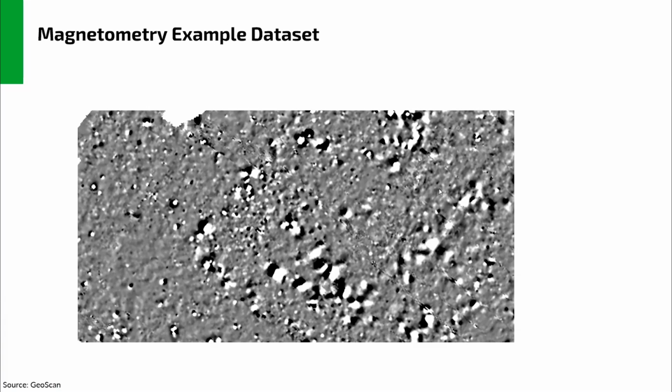But what we're really interested in these cases is the context. If you plot the preliminary interpretation on this, you see some sort of variations. This actually turned out to be a building outline. We have GPR data sets from the same area, and we see the same variations. And then we got information that indeed there was a building there before.